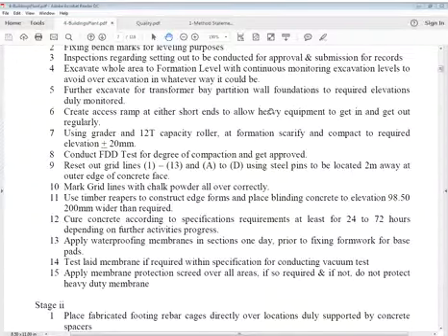You have to put some, it's a maximum 75 mm, 100 mm, 50 in between this range. But it should be straight better on that approved layer of soil. You have to do blinding concrete. Blinding means, meaning of blinding, I think. Whatever elevation is there, wherever a foundation has to come, keep some offset, let us say 200 mm wider than required, so 100 mm on this end and 100 mm on that end. Then you have to cure this concrete according to specifications, requirements, at least for 24 to 72 hours, depending